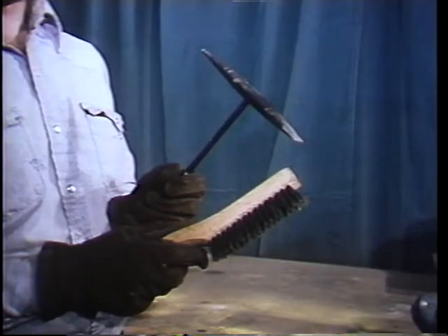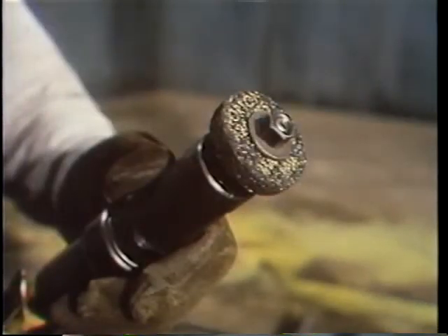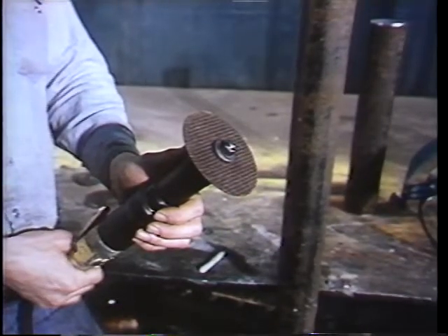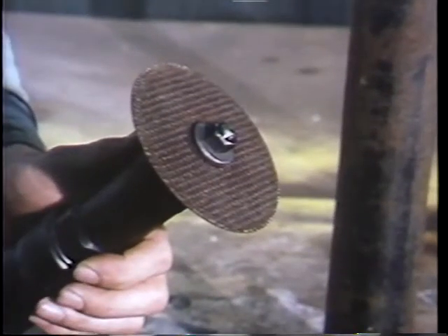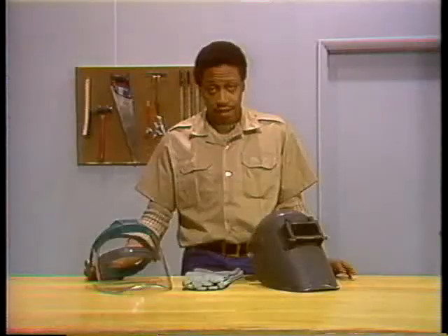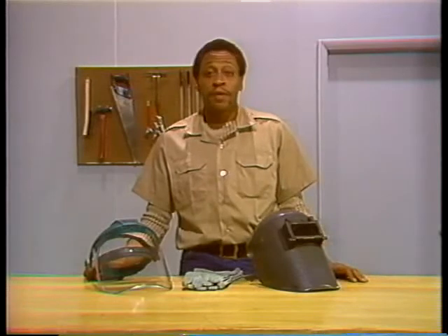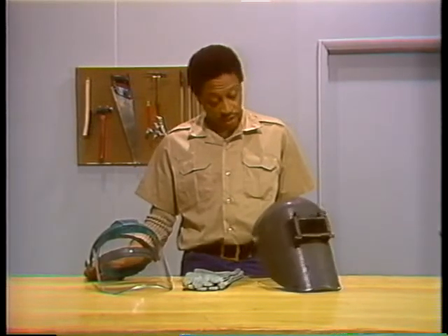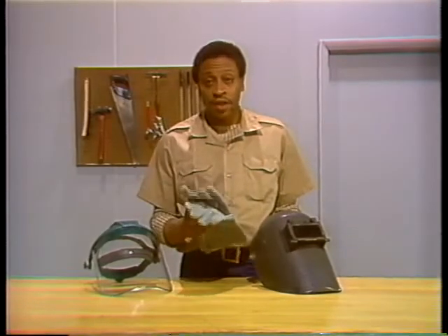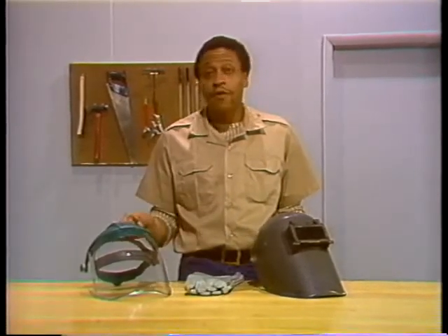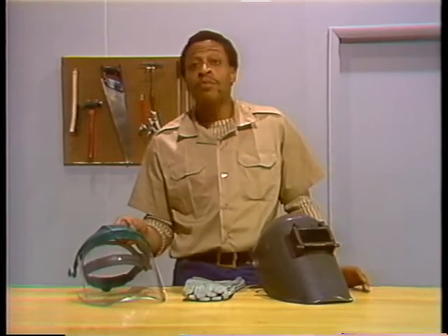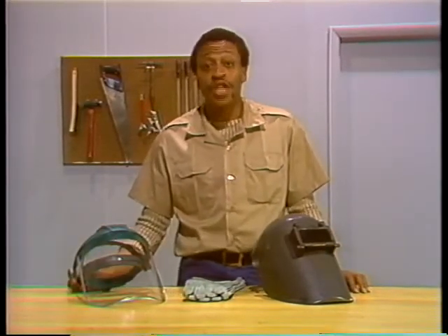You'll also need a grinder and a cutting wheel. This is used to cut out the damaged piece of tube and may also be used to cut out the replacement piece. Now, the same protective equipment mentioned before is necessary when making window repairs. A welding shield and welding gloves are needed, and so is a full face shield when the grinder is being used. Your safety manual may list other precautions, so be sure to check it before you start working.